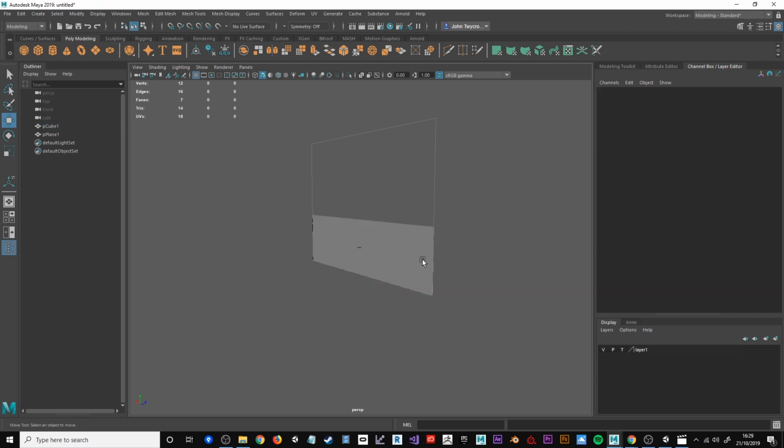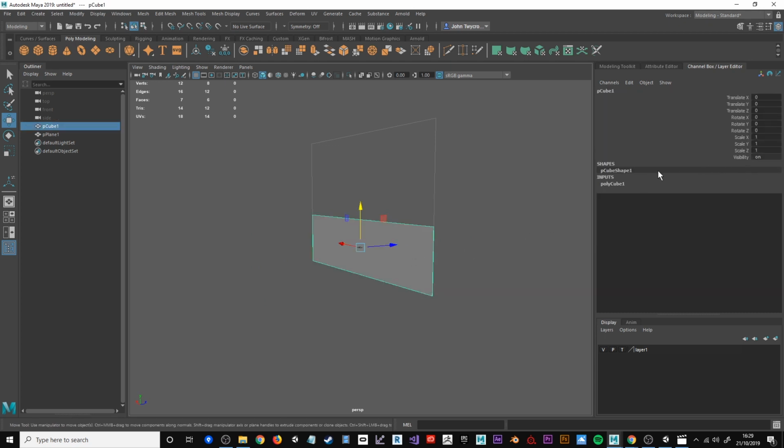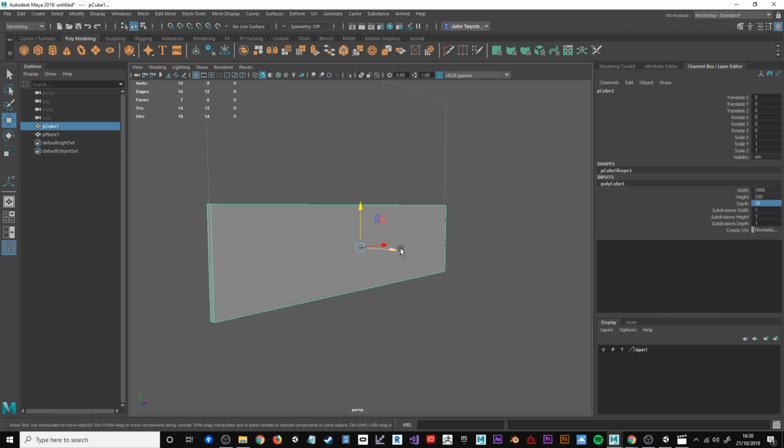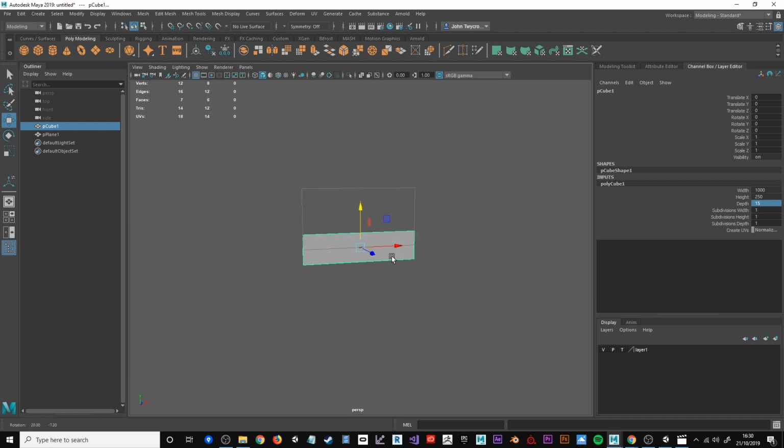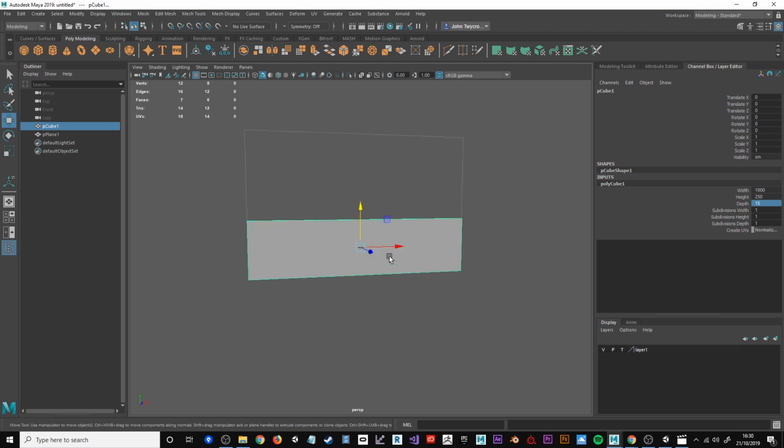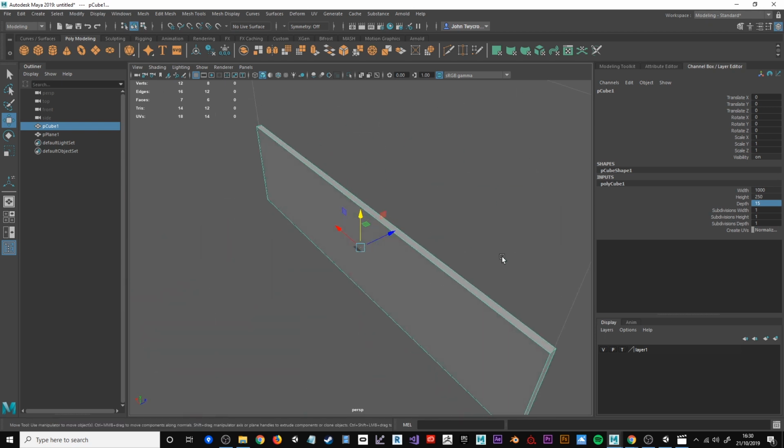But in this case, because I'm using a cube, I'm getting a face on both sides. So I do need to give it a depth, so I'm thinking like a couple of bricks worth is going to be, let's give it 15 centimeters. So now those faces are separated more, I don't get that same interference between the faces. You'll also see there, you're getting that sort of black line coming over the top, because it's just calculating the back face, this face instead.